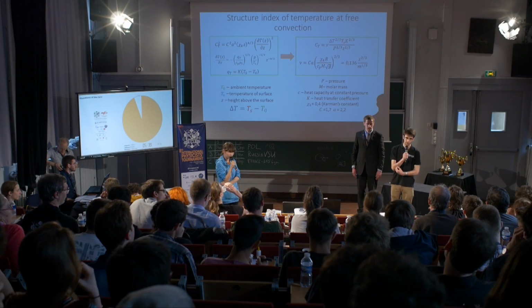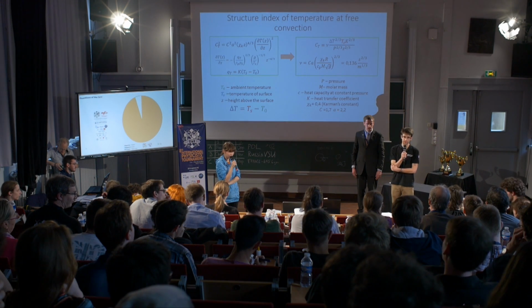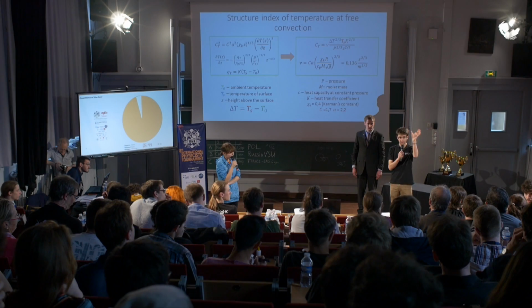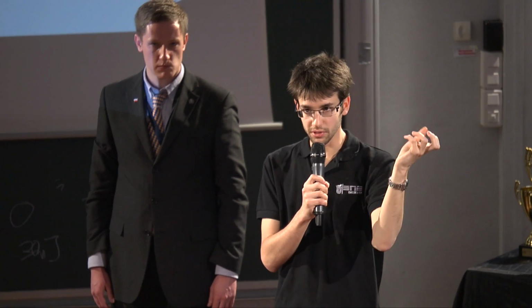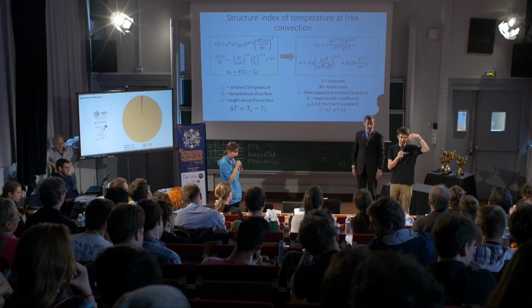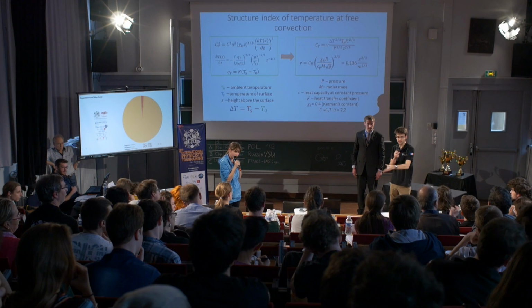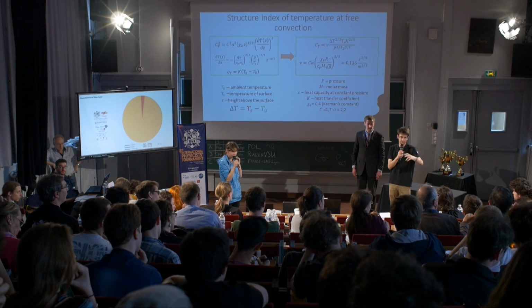Actually, yes, because we concentrated on the upper part of the flow. We also must consider that the Rayleigh number is lower at our temperatures between 10 and 100 degrees. We concentrated on a more laminar flow on the upper surface of the heated air, and by measuring the speed of these amounts of air rising, we had an experimental dependence of the speed of rising as a function of the temperature of our plate. And so we plotted a calibrating curve, which lets us determine the temperature for another plate, because we also tested it for several materials.